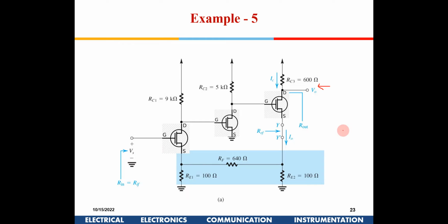Voltage, correct? We are sampling voltage and giving current, right? So in the input circuit, what will happen? Input side, since it is a current, I will remove this, right? So the 100 ohm, this all thing will go in series into this, and this will become parallel out here, right?